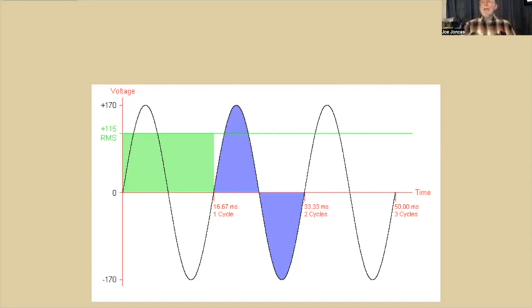Remember the formula that I said you have to remember? Power equals? Does somebody tell me what that formula is? Power equals E squared over R. Right. The FCC has said that we can have up to 1,500 watts peak envelope power. And we figured that out by taking E squared over R, except that we don't use the peak.